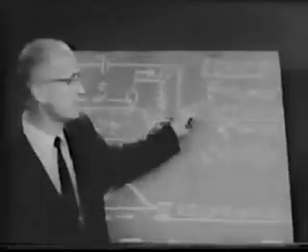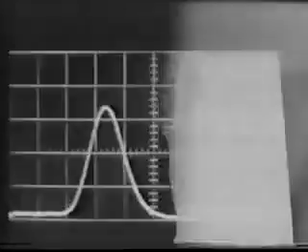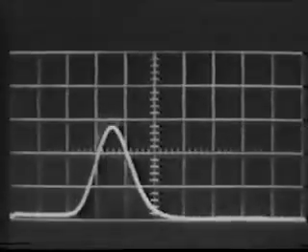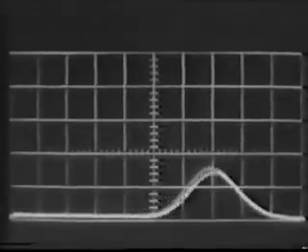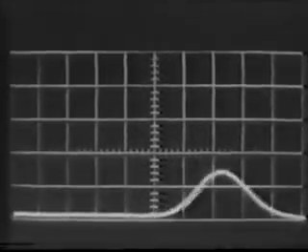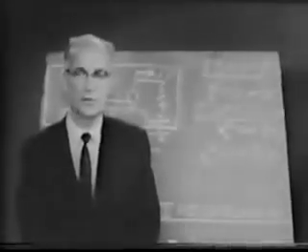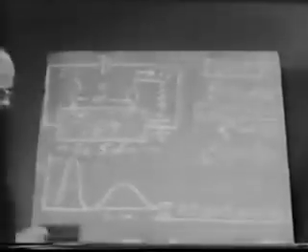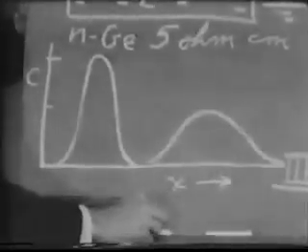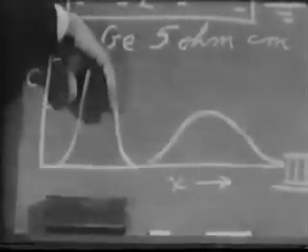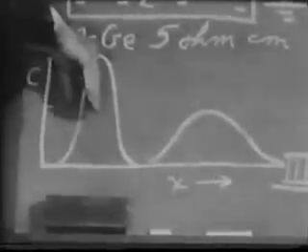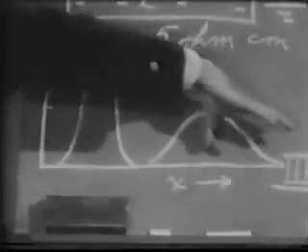Our second experiment is concerned with the shape of the pulse. You have noticed that as the delay time increases, the pulse becomes shorter and fatter. To understand this, we consider hole concentration as a function of distance. When the holes start out bunched together in a narrow pulse, there are big concentration gradients, and diffusion spreads them out rapidly as they drift down the bar.